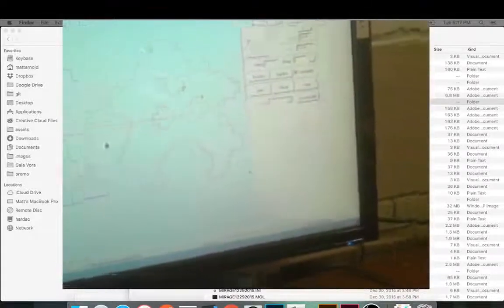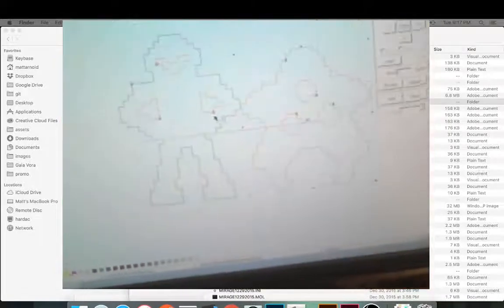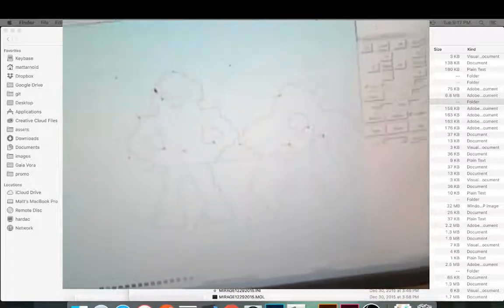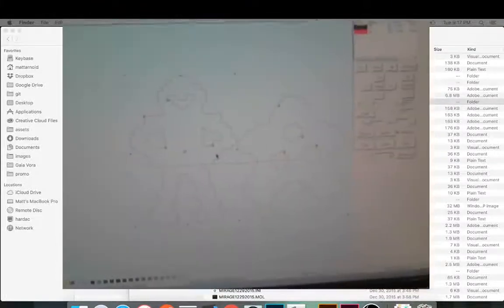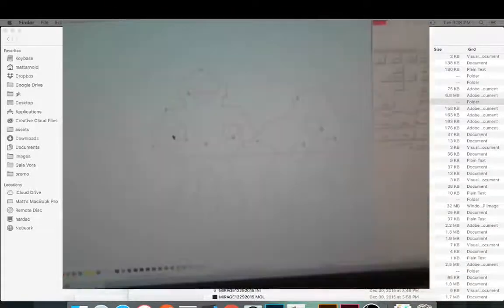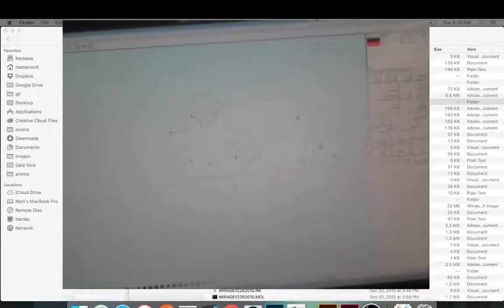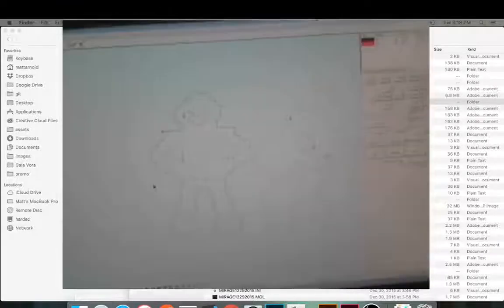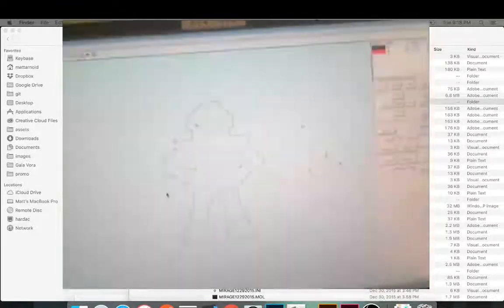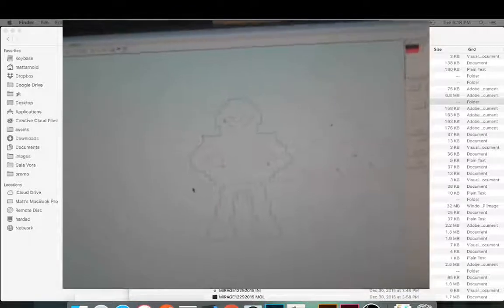All right, so notice that this is red and this is black. Remember how I had Adobe Illustrator open and I said color doesn't matter? Well, it only matters to put stuff onto different layers. So let's say if I wanted to do an engraving on one of these, but I wanted to do a cut on another, maybe I'd need different layers. And so by making them different colors in Adobe Illustrator, I can sort them and group them so that they come in those groups automatically.